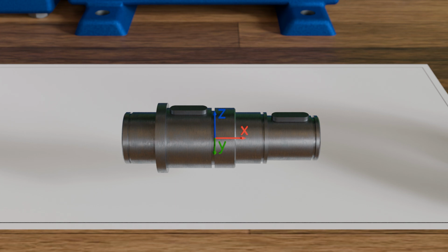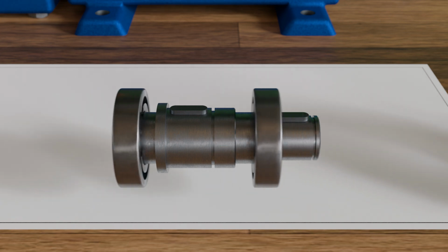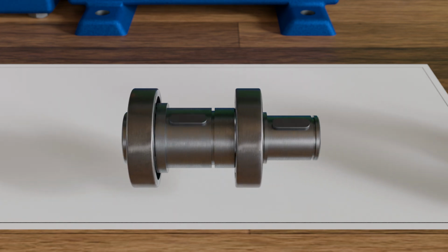The function of bearings is to selectively restrict certain degrees of freedom so that only the movements necessary for the function are allowed. A gear shaft, for example, is supported in such a way that it is fixed in space and can perform only a rotational movement around its longitudinal axis. It therefore has only one rotational degree of freedom. So note, bearings have the task of selectively limiting degrees of freedom in order to reliably enable desired types of movement. Special types of bearings designed for movement with minimal friction are called rolling bearings and plain bearings.